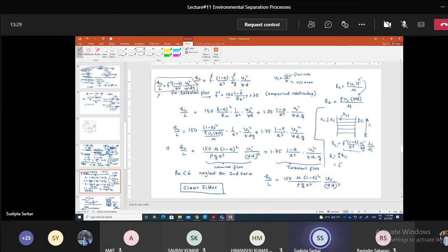You can see the Re formula also has the D incorporated in it. So for each layer, this F dash value will change. So what we should actually write is that you can make this little change in the formula that I have written. So this F dash actually is a function of the D. So we will write F dash i here. Okay. So this is F dash i for this particular bed. So we have a different F dash for each layer.